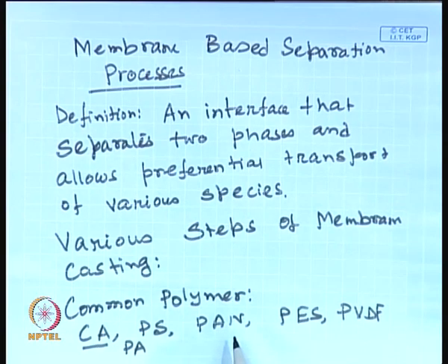We generally look for a property which is typical for the membrane and very useful for separation of solutes. What is that property? The property is hydrophilicity. The membranes are supposed to be very hydrophilic, then they will be more selective for a particular species. For example, most of the pollutants are hydrophobic in nature. Organic pollutants, dye stuff and other pollutants are generally hydrophobic. So we would like to have a membrane which is hydrophilic, so it does not like the environment of hydrophobicity.